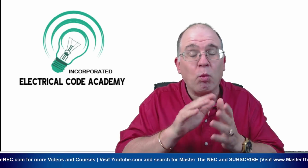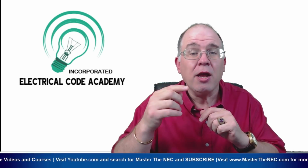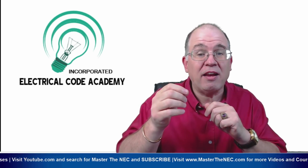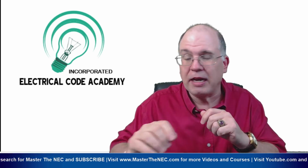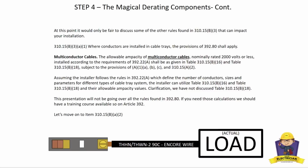So keep that in mind. We're not going to go over those because the ampacities in 392.80 might have to do with the spacing, the number of conductors, and the application of a percentage lower than what's in 310.15(B)(16). So you have to keep all those things in mind. This presentation, we're not getting into those right now. But I did want to make you aware of it. That's what this one deals with.